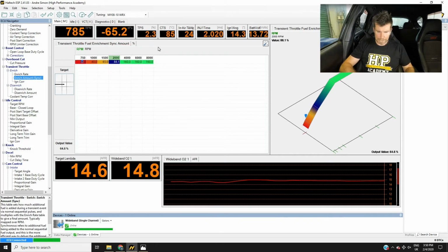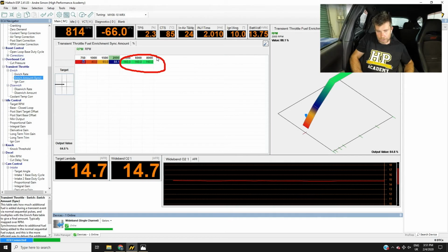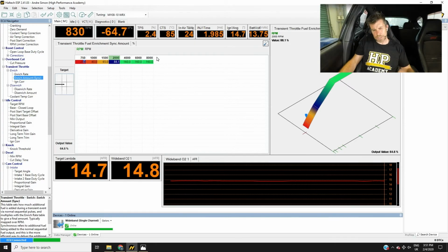that fuel film. So this seems to be a little bit counterintuitive, because we can see here our numbers are actually maximum at high RPM. This is a relatively default table, and you can see the numbers in there from 4,000 RPM and above 160%. So in order to get some clarity on this and make sure that I am giving you completely accurate information, I actually went to the trouble of having an in-depth chat with the tech team at Haltech earlier today.